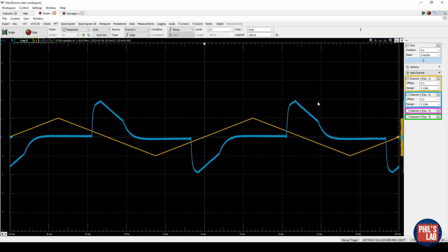So as the input goes down, we can see this in the blue output trace over here. And once it reaches this threshold value again, we have a slower attack low-pass filter working. So you can see this exponential decay is much slower than this release exponential increase over here. So we have different orders of magnitude in the low-pass filters when we smooth the gain. So here's the attack stage, and here's the release stage. And then we just clamp it down to 0.